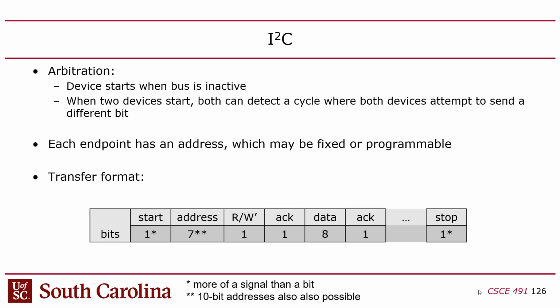Okay, so just to back up here. There's a separate acknowledgement for the header part. I don't know what you call that, the first part of the transaction. There's an acknowledgement, and then there's an acknowledgement for the second part of the transaction. So there's 2 acknowledgements. If you get a NACK, which is a not acknowledge, after the first part of the transaction, then you just have to bail out. You're like, no, this is not going anywhere. And why would that happen?